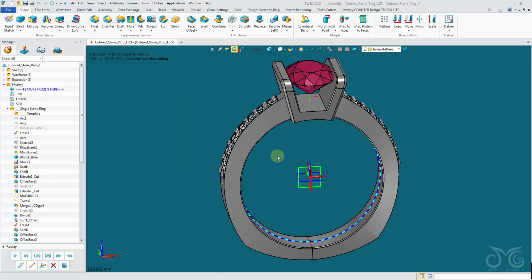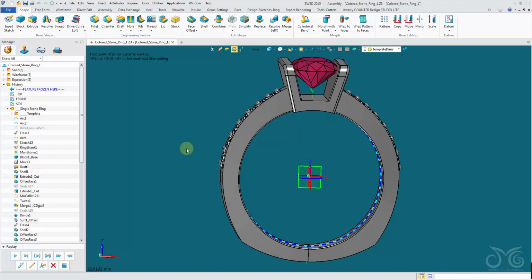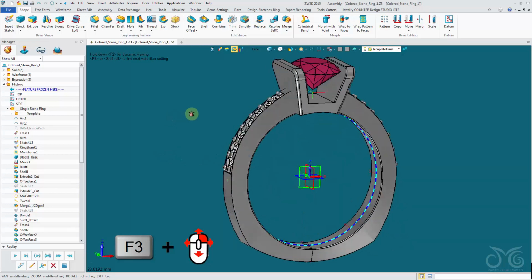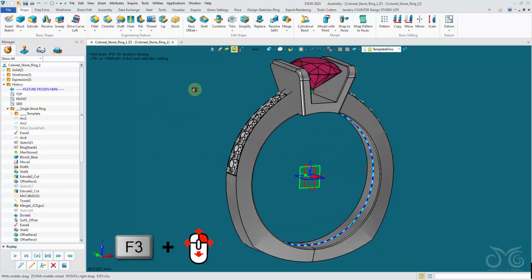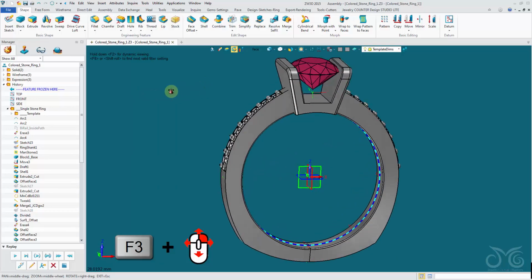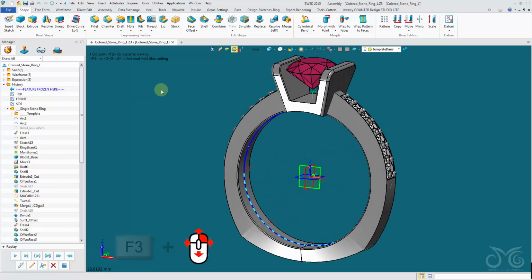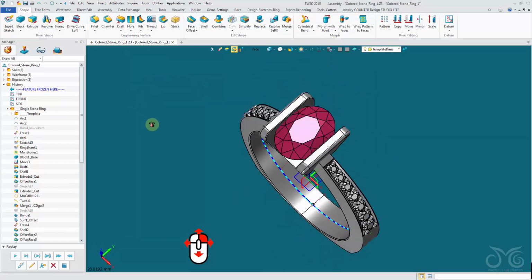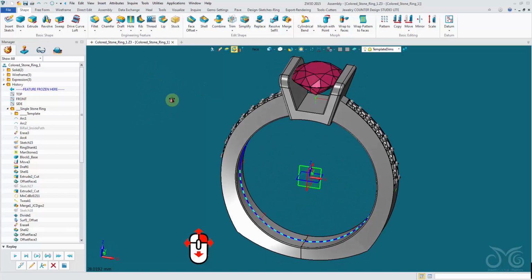Okay, a couple of other hotkeys that aren't in that hotkey panel for whatever reason are our F3 and F4 buttons. Holding down F3 and then using the right mouse button to rotate our object, we will rotate about the view axis. Okay, in this case the Z axis. Okay, our rotation normally allows us to rotate dynamically like this.